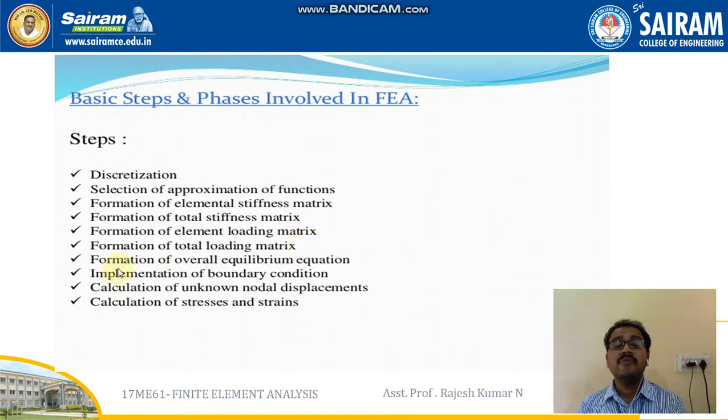The next step is formation of the overall equilibrium equation. The equilibrium equation is almost common for all structural analysis: K into U equals F. K is the global stiffness matrix, U is the displacement matrix, and F is the load matrix or force matrix. The next one is implementation of the boundary conditions.